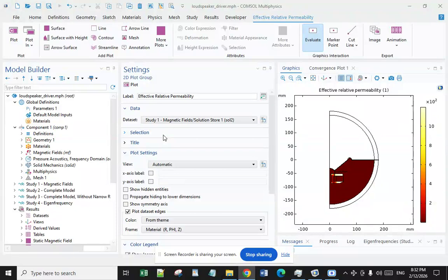The AC current in the electric coil induces an AC magnetic field and thus produces magnetostriction at an ultrasonic frequency in the material. The disturbances caused by magnetostriction then propagate in the material as an ultrasound wave. In polycrystalline material, the magnetostriction response is very complicated. It is affected by the direction of the bias field, the direction of the field from the AC electric coil, the strength of the bias field, and the amplitude of the AC current.